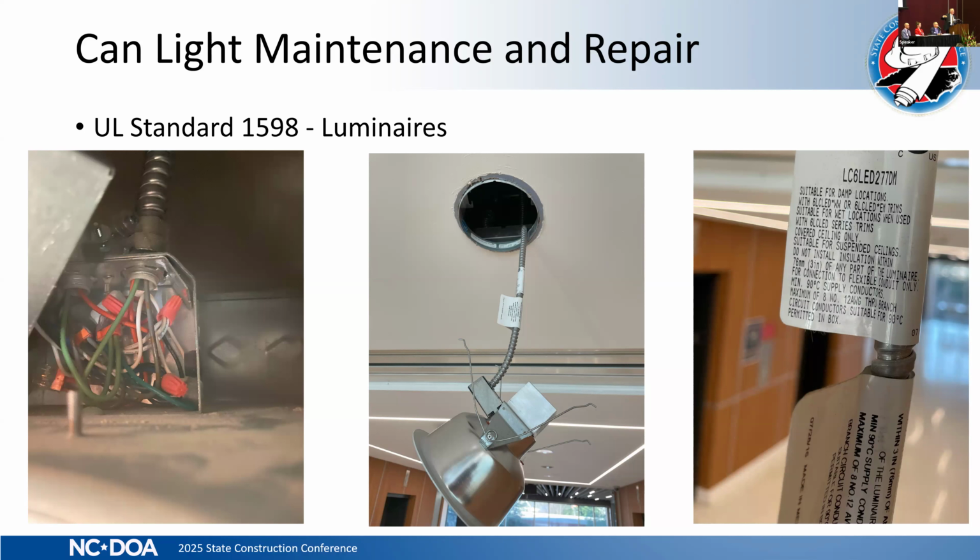Is that a suspended ceiling? The contractor said, well, of course it's a suspended ceiling. Otherwise, it'd be a floor. Right? So it's not a suspended ceiling. A suspended ceiling is like what you have in this room with tiles that drop in and the tiles are suspended. So we've got some problems with definitions, which is probably why UL doesn't want to talk about it either.